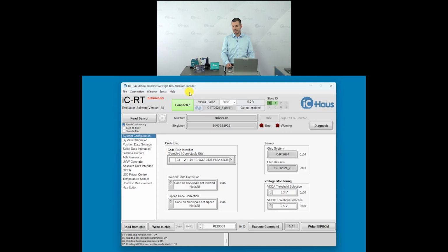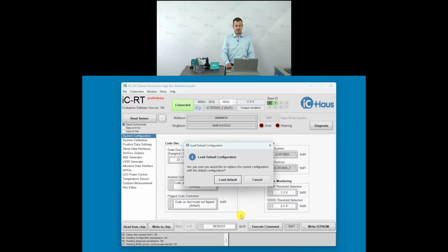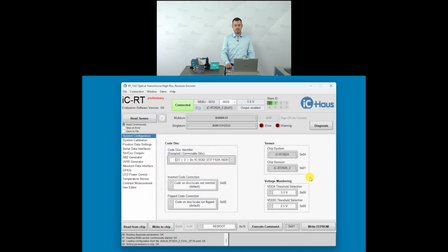Okay, LED illuminates, blue light, 460 nanometer, and now I can program the chip. To be fair, I'd like to have the same default configuration that you would have when this device is delivered. So I just go to File, load a default configuration file, up into RAM.